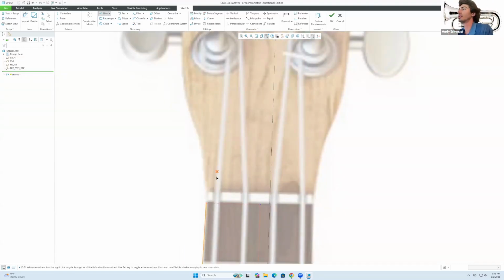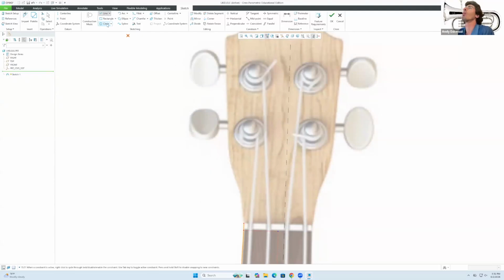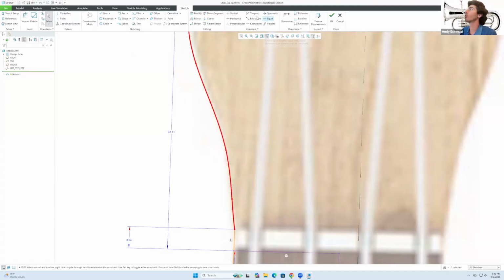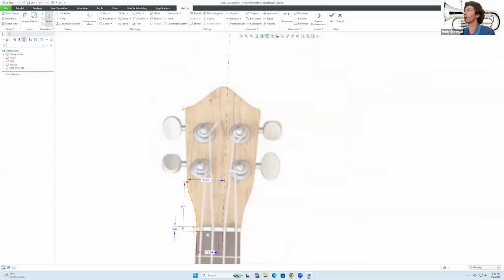That's great. Let's see whether I can go all the way like that. So just like a little thickness that you have in there. And now I'm going to use again the spline. I will use it, there we go, to mark those points. And one thing that I can do is go to where it says tangent, clicking that line, and clicking that line, and see how it's saying it's like equal curvature, which is a very nice thing. So that's working well.